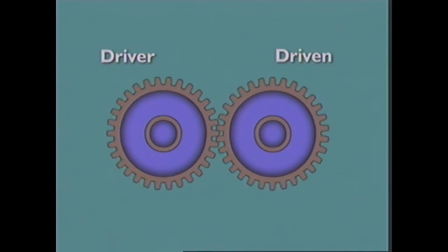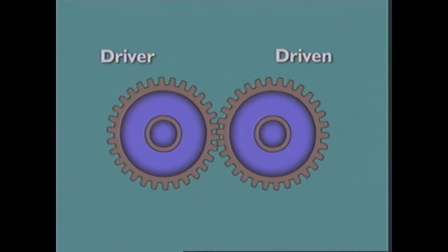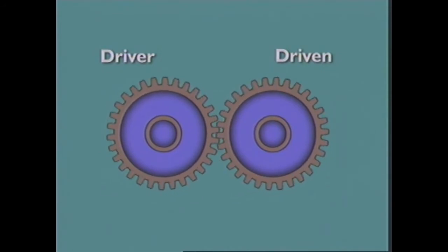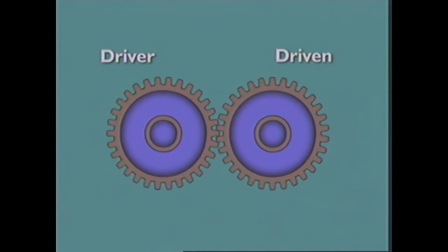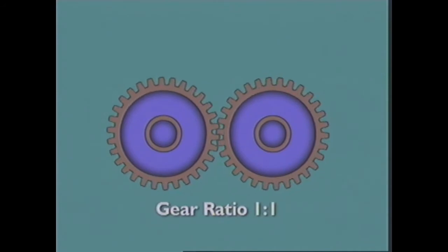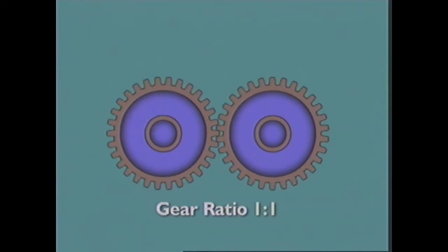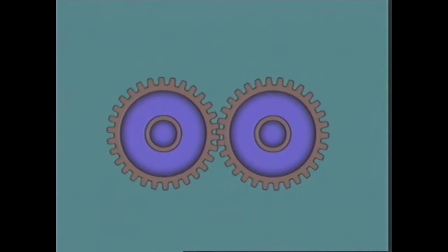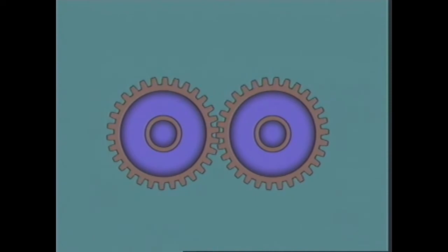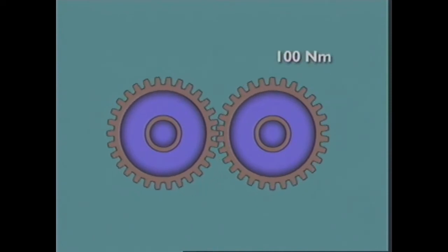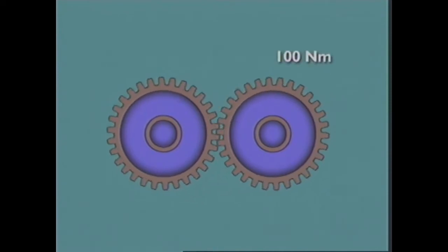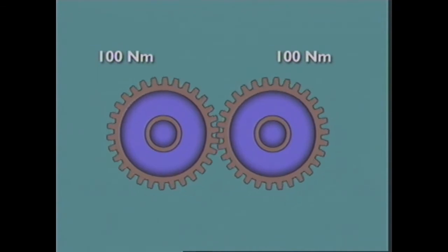A gear ratio is the number of turns of the input gear necessary to achieve 1 turn of the output gear. Here it is 1:1, since the gears have the same number of teeth. In rotation, they also turn at the same speed, and the turning effort of the output gear will equal the effort applied by the input gear.